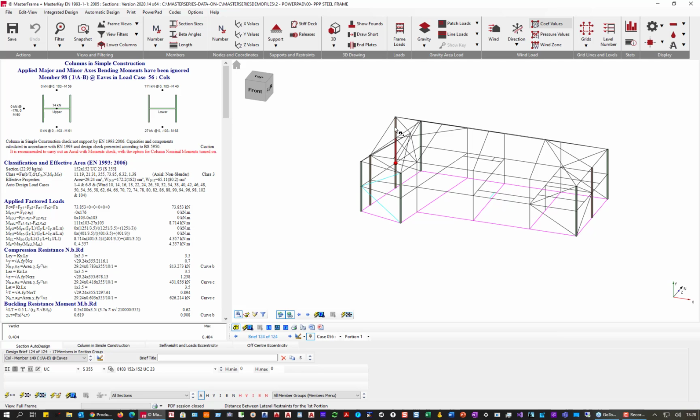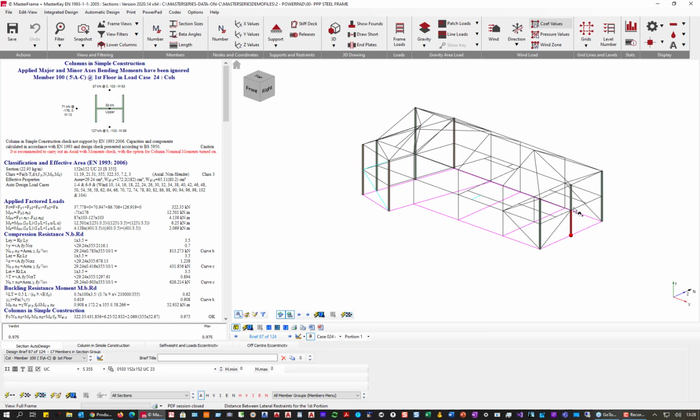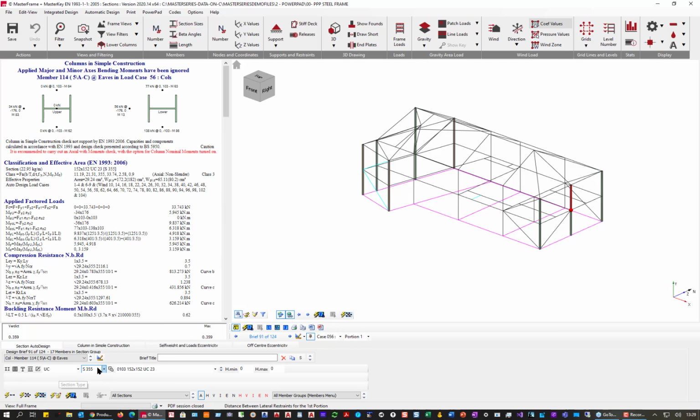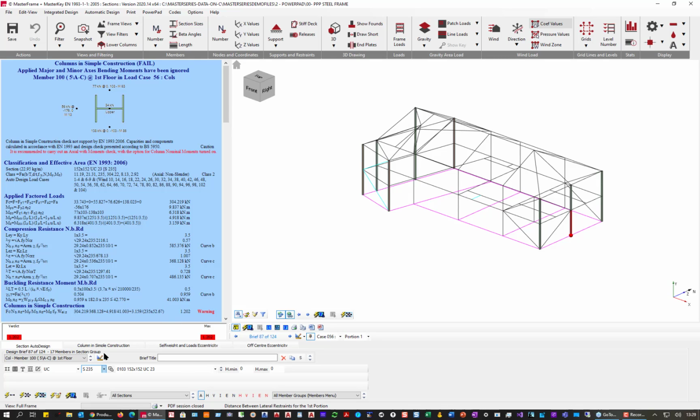I think putting that vertical in there has now made it work, but not to worry. If I took this, okay, I'm already at the 15223, so I want the light section. If I went to this one and reduced it down just, for example, to a 235 grade of steel, that's just working and no more. But down here it's not going to work.